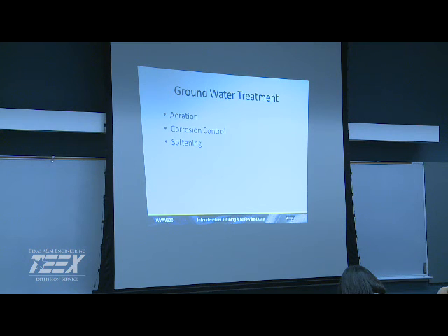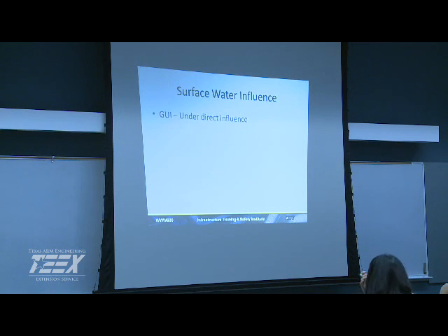Typically, groundwater is more stable than surface water. We're going to have more minerals in it, so it's a better water quality. Sometimes they actually need to soften it; we don't, we did just the opposite. Then you get into special processes, which is basically surface water treatment if you're going to do coagulation and all that. Or you can use RO if it's a real poor water quality.